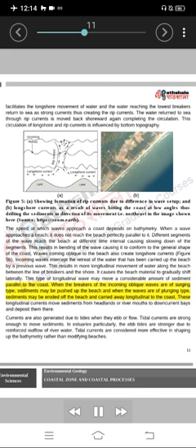When the breakers of the incoming oblique waves are of surging type, sediments may be pushed up the beach, and when the waves are of plunging type, sediments may be eroded off the beach and carried away longitudinal to the coast. These longitudinal currents move sediments from headlands or river mouths to downcurrent bays and deposit them there. Currents are also generated due to tides when they ebb or flow. Tidal currents are strong enough to move sediments. In estuaries particularly, the ebb tides are stronger due to reinforced outflow of river water. Tidal currents are considered more effective in shaping up the bathymetry rather than modifying beaches.